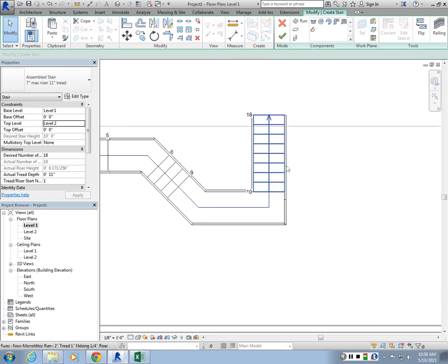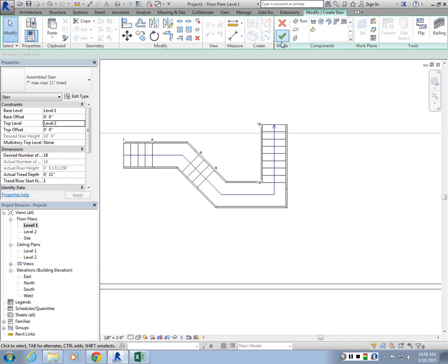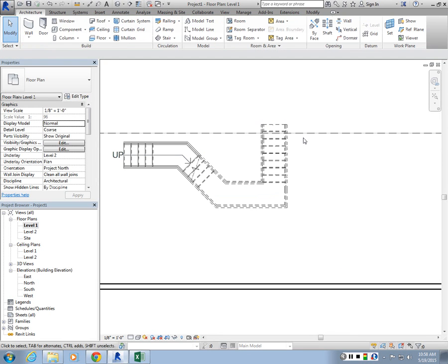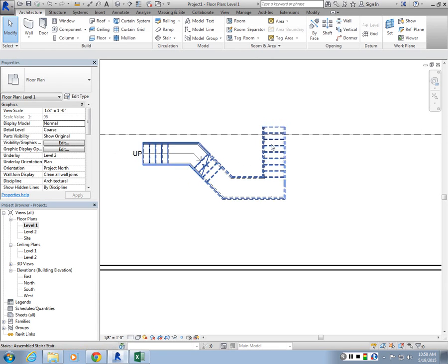But by the time you added all the risers for the staircase, you need to exit the staircase so that you can create a new one. Because if you're still active in this staircase and keep putting risers somewhere else, it will try to connect them. Okay. So you need to think of this as a single object.